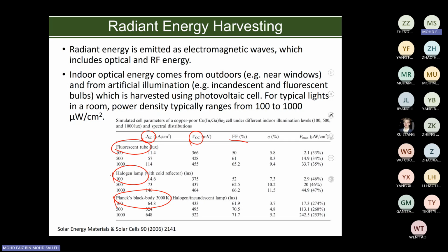And usually when we discuss energy harvesters, we will discuss power density per volume or per size. So if you are using photovoltaic, you need to have a big size. So in terms of power density, it's not very good. If you use thermal, the size is not really important, but how to keep the temperature. Maybe you can meet in terms of power density.